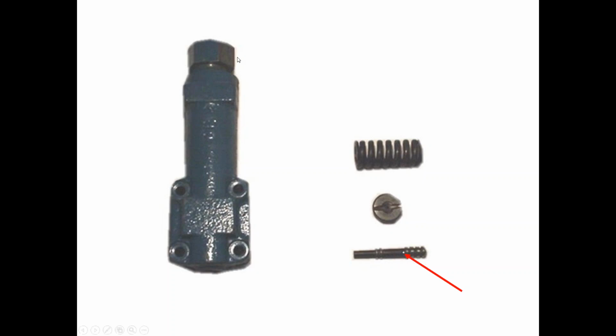Okay, granted, you have to lock it out and everything. You got to do that for whatever you're doing, though, so we can't really count that. You could probably do this faster than you can walk over to the storeroom and see if you've got another pump. Okay? Probably talking just a few minutes here. So at the very least, before you change a pressure compensating pump, pull the compensator spool and see if this is plugged up. You might save a $15,000 or $20,000 pump by doing that.